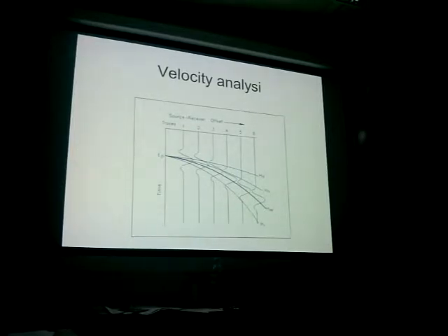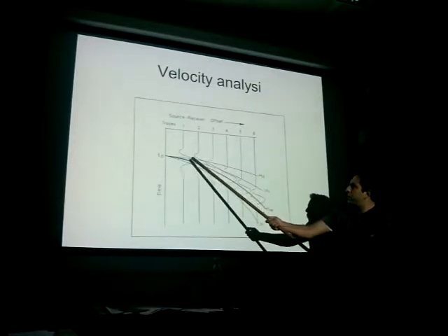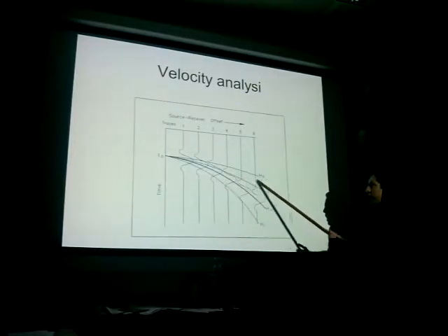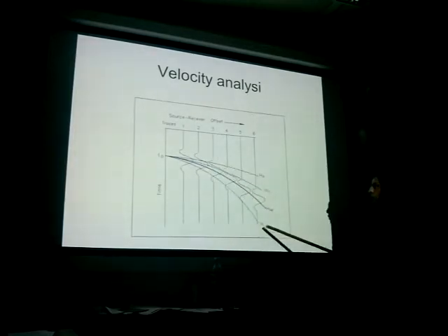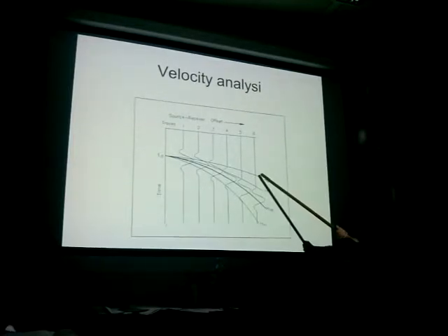So at a certain point you decide to use a best fit of your hyperbola, but you can have several possible hyperbolas approximating it. One is passing through that point, another through that, another through that. What is the difference between those hyperbolas? The velocity. Only one is the correct one, and only one has the right velocity. If you assign the wrong velocity, you are not correcting the hyperbolic conformity. If you assign that velocity, you are overcorrecting your hyperbola.